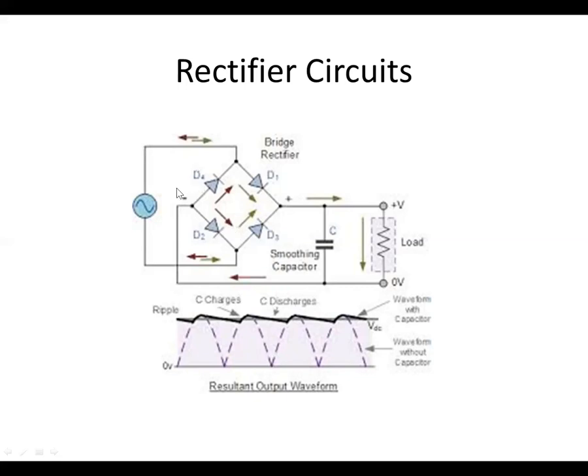If we didn't have the bridge in there, the AC signal would have just been what we're used to seeing. So this takes a positive and negative AC signal and converts it to a pulsed AC signal, always being positive in this case. Now, where the current goes then is to a smoothing capacitor.